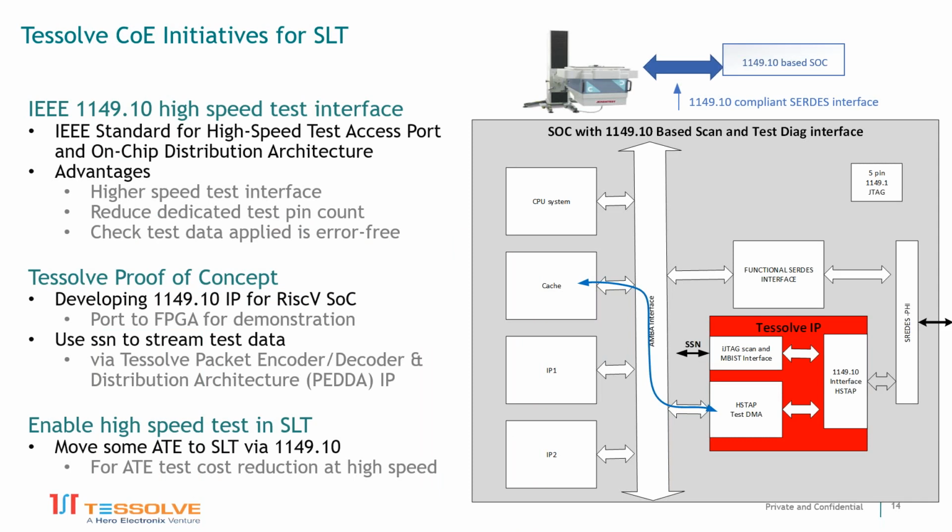Because one of the things we're working on with SLT is to push more of the structural tests. So before we talked about ATE, and we do structural tests like scan test inside an ATE, and it's very expensive equipment.